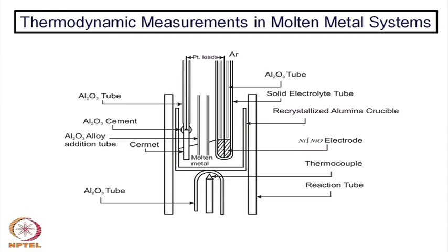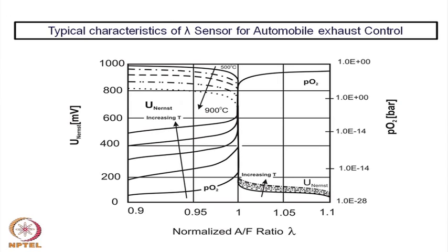Of course, one thing I forgot to mention is that along with the lambda sensor, one always uses a catalytic converter. The exhaust gas is allowed to flow through it, and it has certain catalysts, normally some noble metal catalysts, and they catalyze the remaining carbon monoxide into carbon dioxide. So, no carbon monoxide actually comes out, although you cannot avoid the release of carbon dioxide. Even after this control, a small amount of carbon monoxide may come up, but that will get oxidized on the catalytic converter.